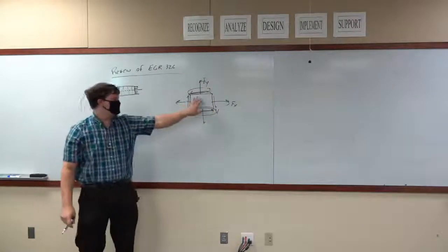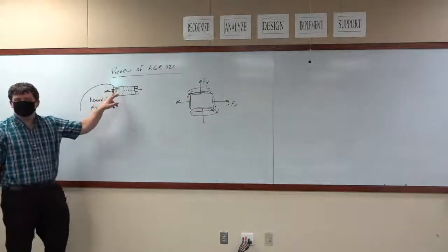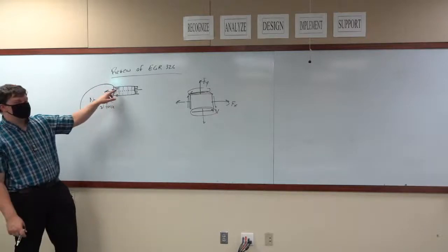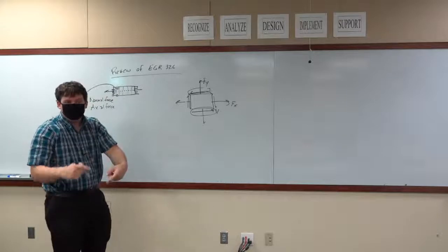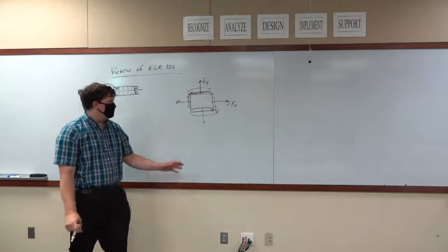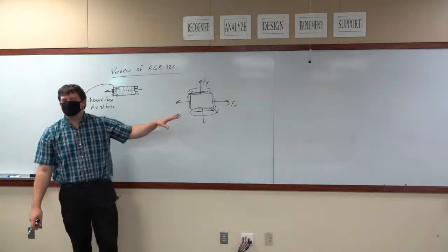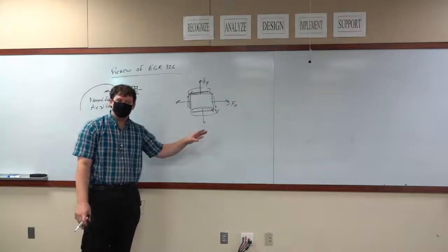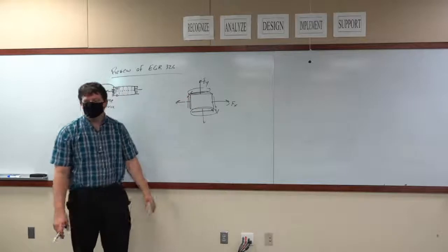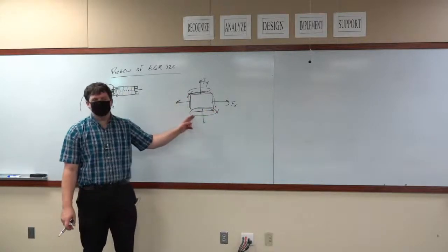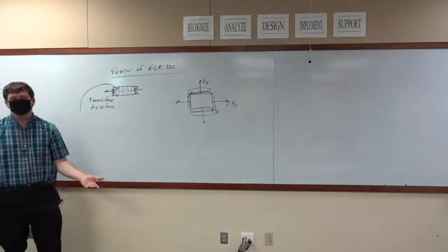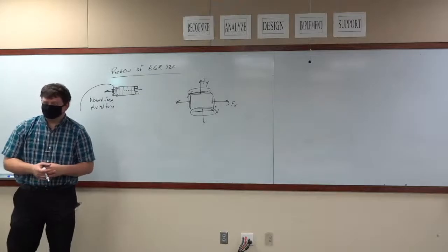If we're taking this square and it's in the center of this material right here, as soon as we start applying a shear force, you're not going to see that square start spinning rapidly. That would be really psychedelic if it did. But it's not being loaded with a moment such that it angularly accelerates. There has to be a counter moment on this, and that counter moment is created by the opposing shear forces. Anytime you have a shear force show up, a moment also shows up. Shear forces come with moments. Why? We'll talk about that in a second.